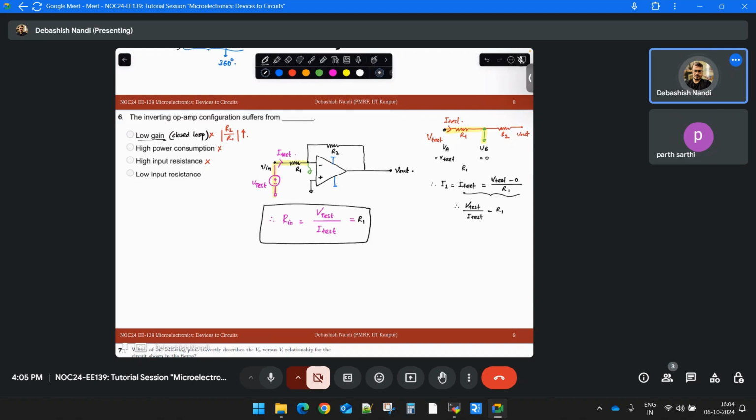Do you get that? Yes, sir. So you need to see what is the current flowing in that branch. Forget about any other branches associated with it. If that voltage is ground, that means this point is fixated. It is equivalent to connecting a voltage source of 0 volt to this node.